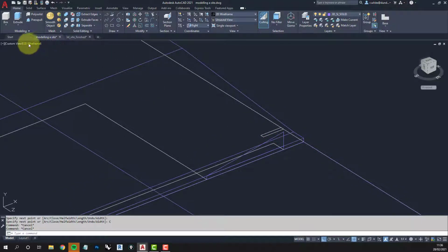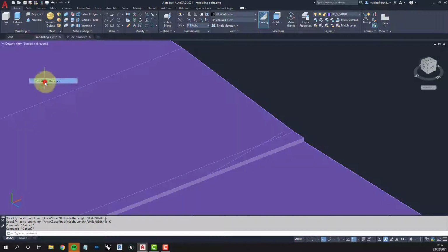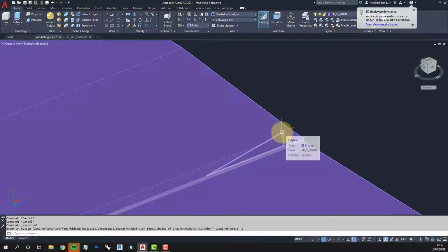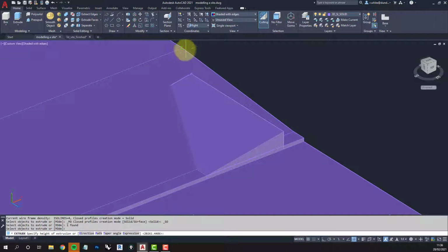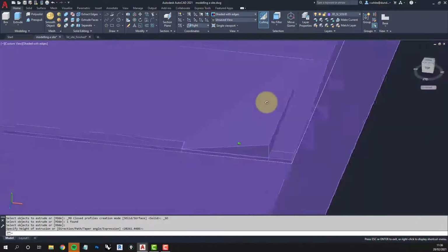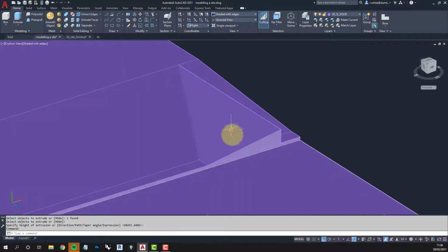Okay, now let's go into shaded view so you can see what happens when we extrude it. It doesn't normally work in a shaded view, but it'll work okay for this. So if we extrude that now back to this point, can you see the way the triangle, we've got this merged shape. Okay, the two are just colliding at the moment, but it's giving us the way that the pavement would have to drop in kind of two directions to get there.